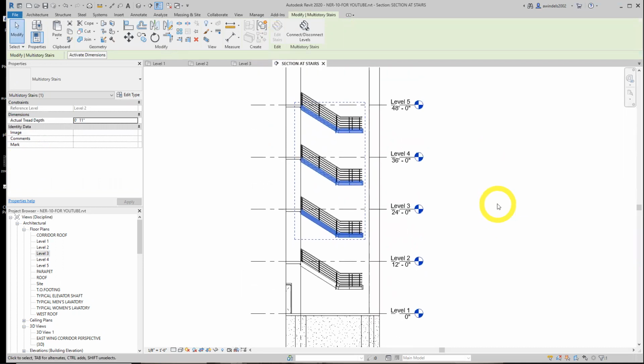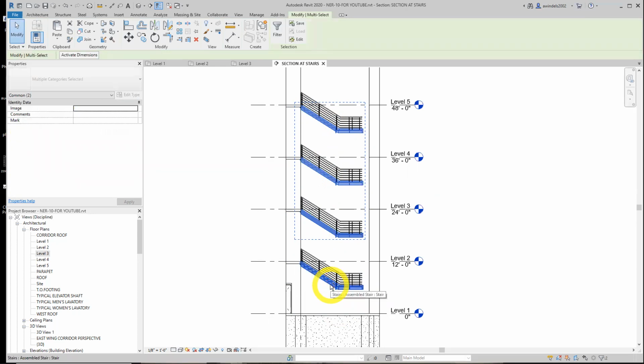Similar picture on 499. So let's hover over stairs, these 4 to 5 here. There we go. You want it to look like this, not like this with anything else. You got to almost hover over one of the stairs in 3, 4, or 5, just like so. So you see that outer highlighted dash line, okay? That's the key. Notice that dash box. When you see that box, pick the stairs. And hold the control key. And now, while you're holding the control key, select the stairs here.